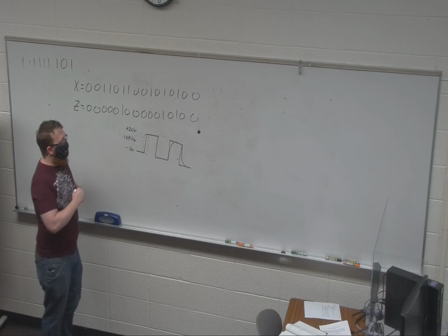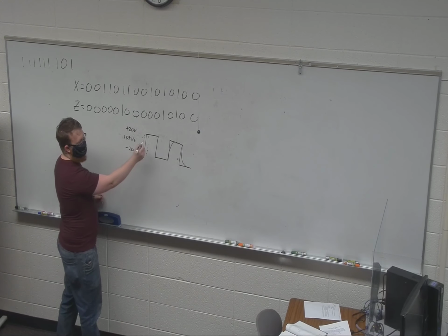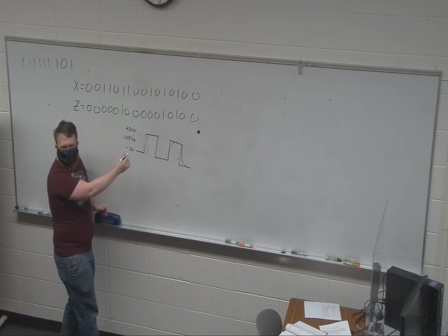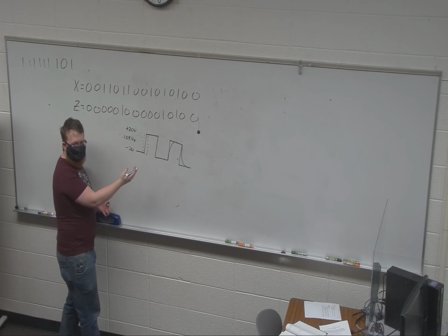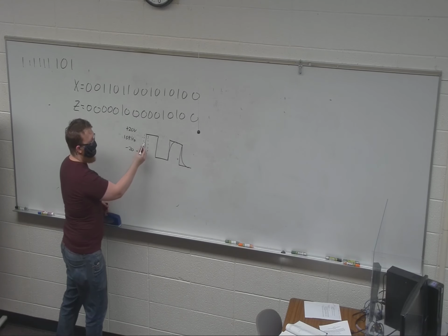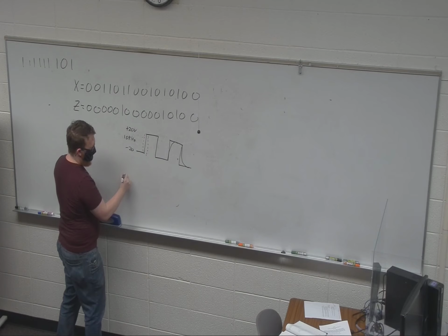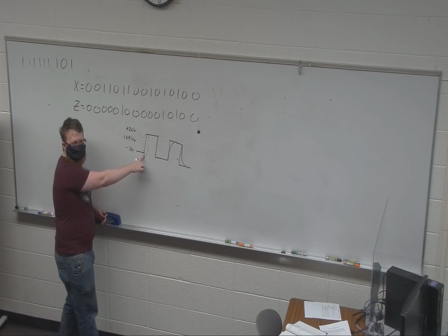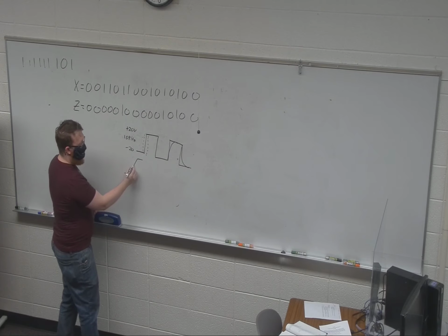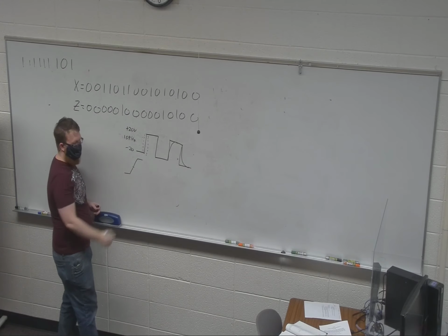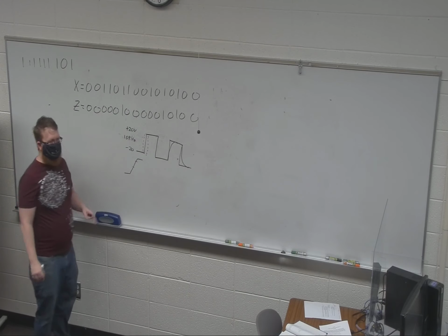And so you already have a little bit of an issue on the transition of when is it a 1 exactly. We don't necessarily know. It'll be specified, but there's a little bit of a difference. So when we're rising, if we're coming up at a slope, right, because this never happens instantaneously, it could trigger here, or it might trigger here.